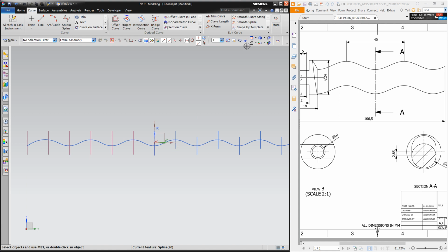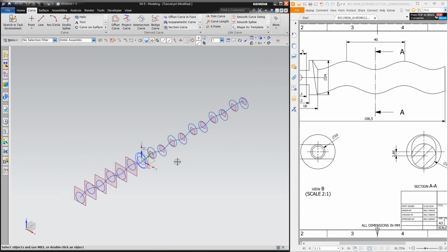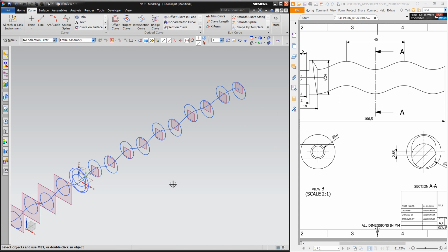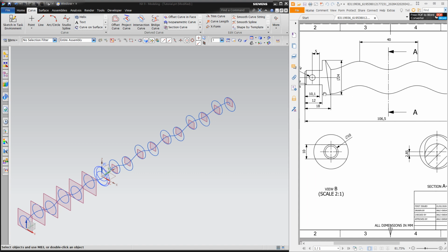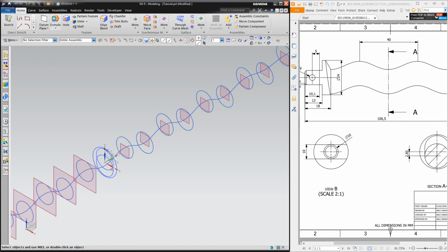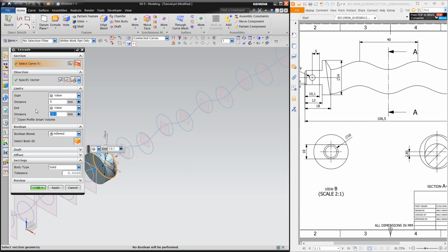Okay. Now this is the position. Now we create the base first. This is the base. Base thickness is 12 and 18, so 6 mm. We go home, choose the extrude command and take this, which is 6, back side, not front side. We take it back side because the curvature starts from here. This is the lowest point, highest point, lowest point, highest point. The distance is not exact, but it is approx 20, just half of 40.